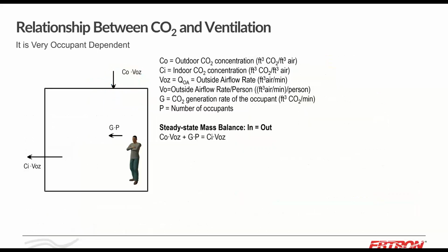So CO2 has been used for a couple of centuries to understand the ventilation rate. And CO2 showed up in the standard in 1989, really for the first time. In the 1989 standard, they talk about 1,000 ppm being a value that should satisfy odors. Well, since that time, CO2 and CO2 DCV has been misunderstood. I'm just going to quickly try to clarify, but CO2 is directly dependent on ventilation.